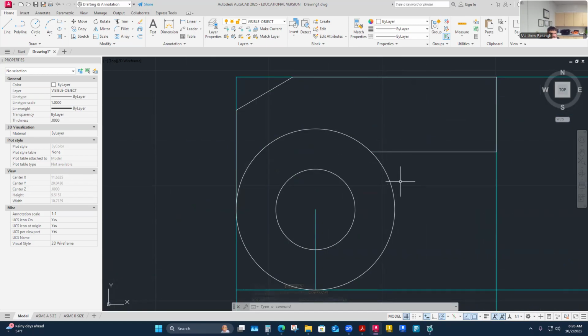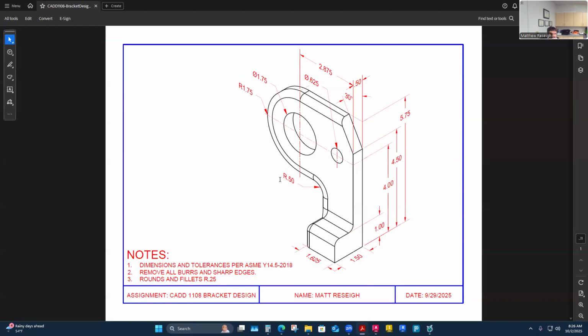I'm going to try my fillet here again. I did this the other day, and I couldn't believe that I couldn't remember in my mind if fillet works against this, and it might just turn this one in. Let me just try. I don't know if it'll work here, but this should be a radius of a 1/2 inch, 0.5, right? Right here. Radius 0.5. I should come out and have a radius back to that 1 3/4 radius. I should have this kind of smooth transition. It probably has a little bit of a straight section because, well, it definitely does because this is where the radius would stop. That's 1 3/4.